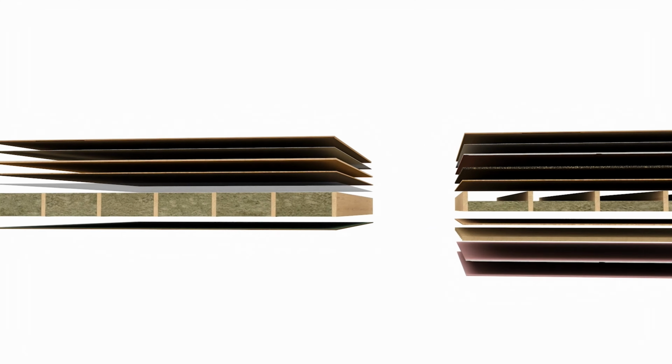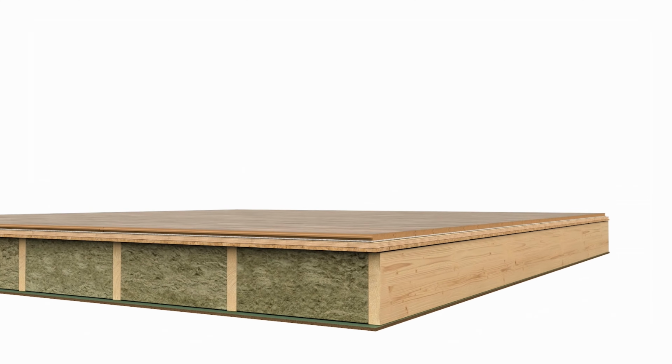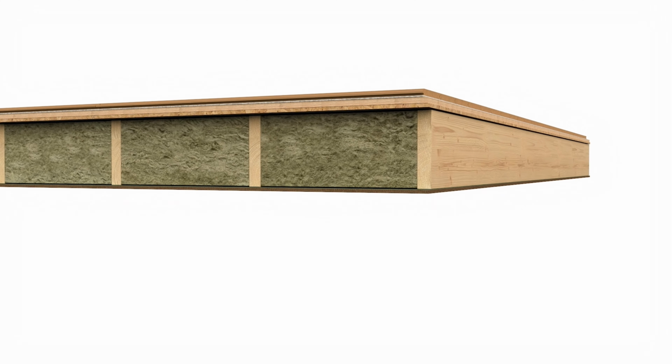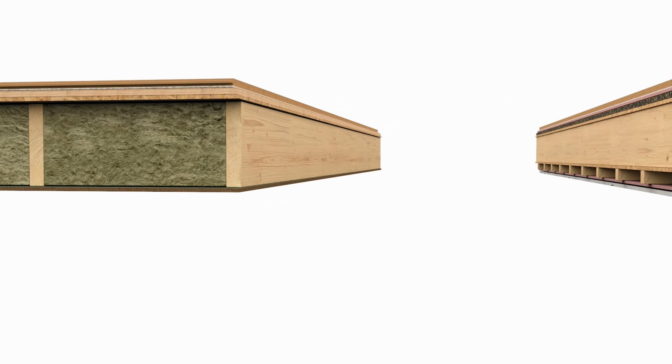And for the assembly of a specific element, it is necessary to carefully study the detailed instructions, both the corresponding work instructions and the production drawings. The floor structures of factory buildings can also vary considerably, depending on whether they are element or modular buildings. For instance, in the case of modular buildings, the intermediate floor is divided into two separate parts: a floor panel and a ceiling panel, but in element buildings, it's a single integral panel.